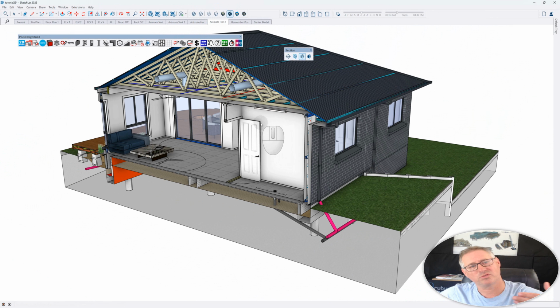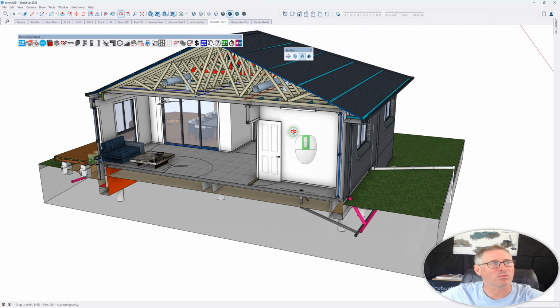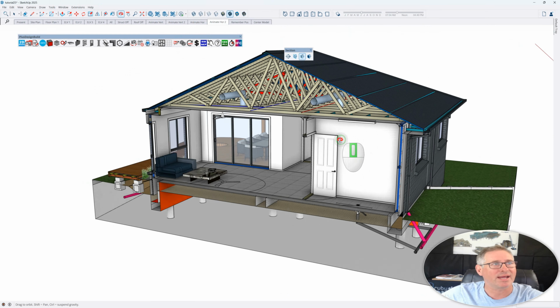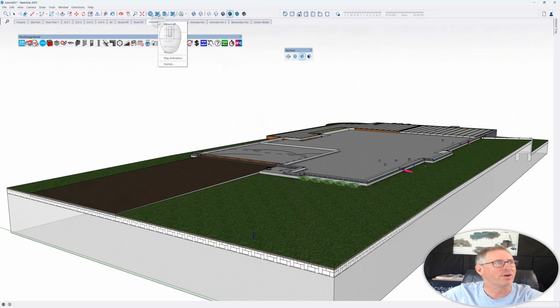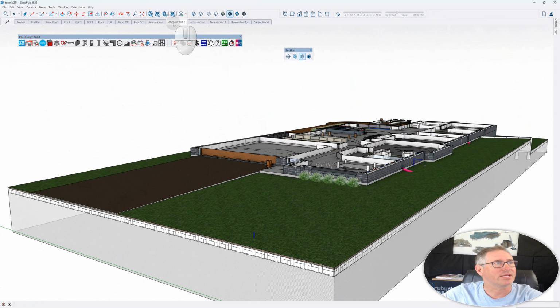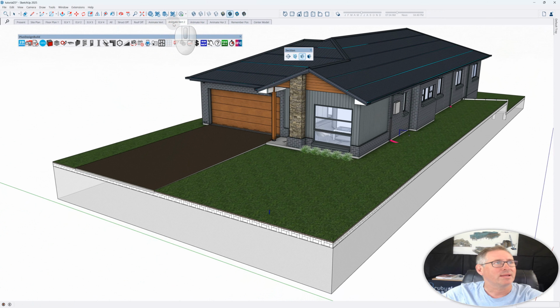Now you might want to reposition this model so that when it actually does it, it turns up here instead. So I just moved it over, right click and Update. If I went to Animation Horizontal, now you'll notice it's centered in the screen a little bit better than before. The same would happen here. You'll notice at the top it's sitting right up here. Really, I want this down here so I get the most out of the visualization. Right click, Update, and then go into Animation Vertical, and you'll notice it does.